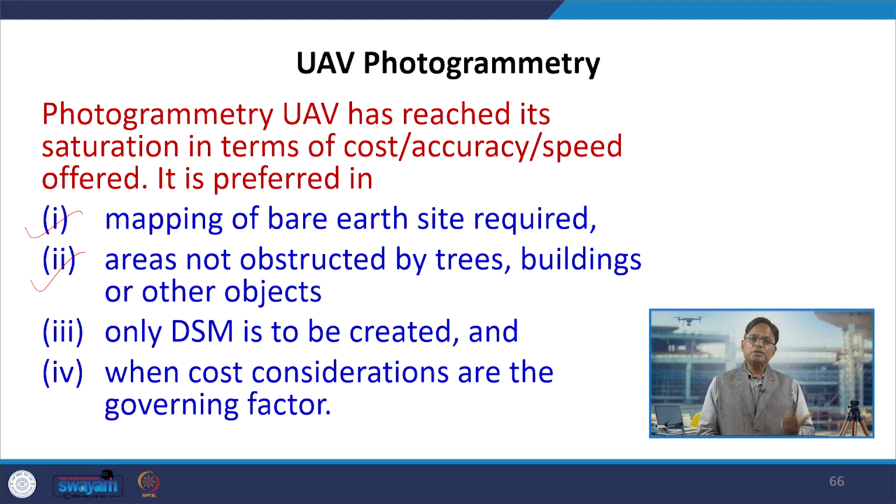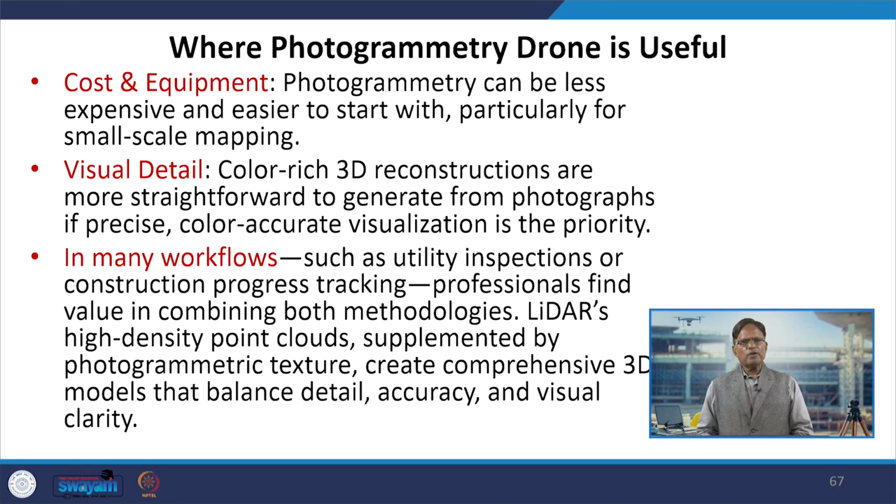When we have to create a DSM, then UAV photogrammetry is a preferred technique. Also, when cost considerations are the governing factor, when you want a low cost solution, then UAV photogrammetry provides a low cost solution. So, where is the photogrammetric drone useful? It is useful when cost and equipment have become a criterion. When we want visual details, which we can identify with our eye and see the details, and in many workflows such as utility inspection and construction progress tracking. So, these are the areas where we prefer the